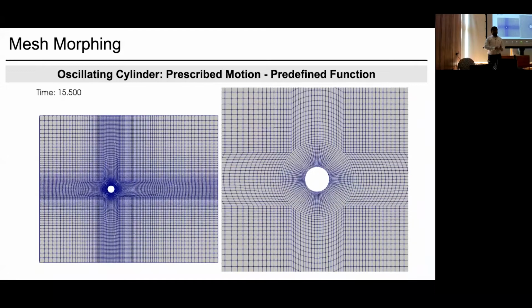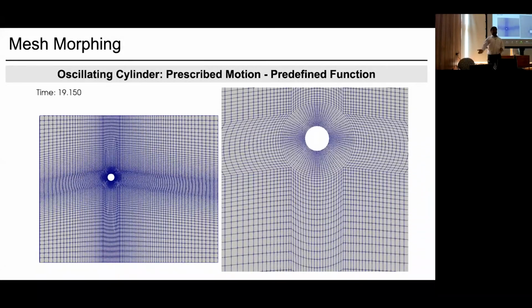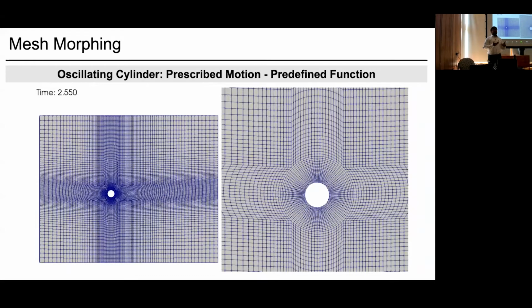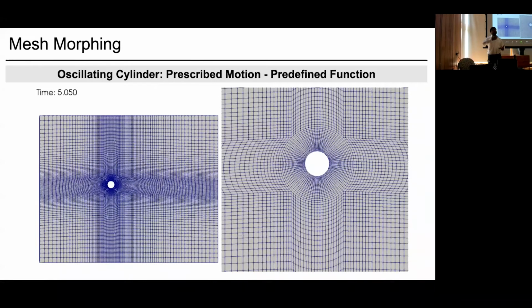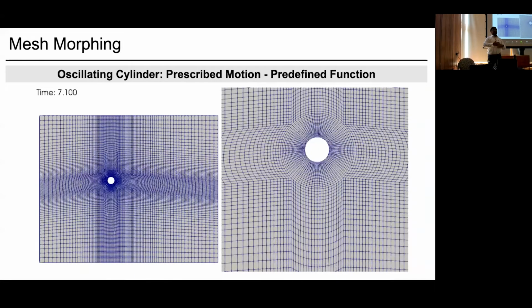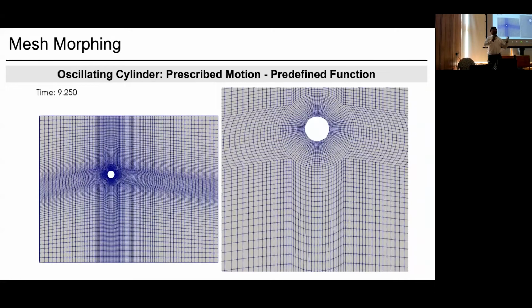That's the reason I will come to another type of mesh motion problem, which is called overset motion. This overset meshing can give you a solution to that, because in case of overset, your mesh is not morphing and one mesh is just gliding over another stationary mesh. Because of interpolation, the solution might not be that accurate. I'm not going to that comparison.